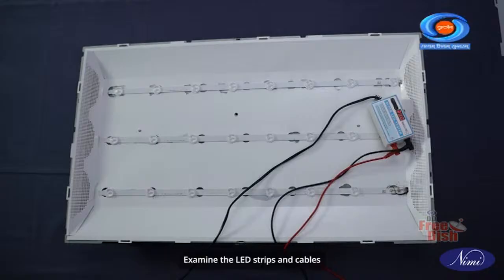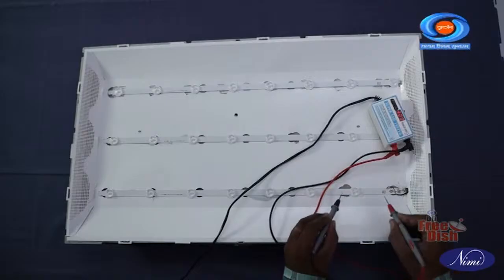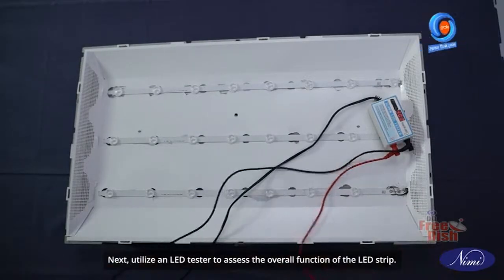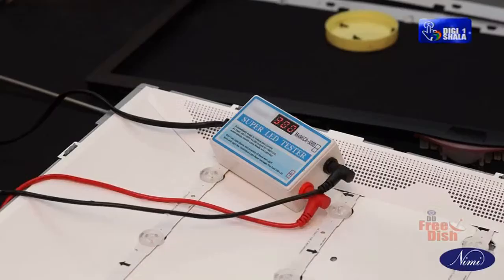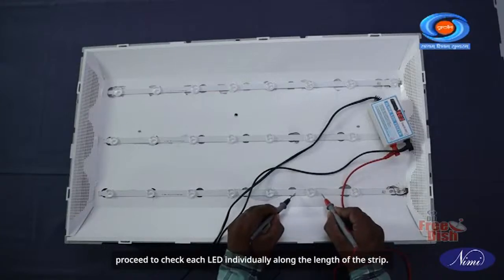Examine the LED strips and cables closely for any signs of damage, wear, or malfunction that may be affecting the TV's performance. Next, utilize an LED tester to assess the overall function of the LED strip. Following the overall function test, proceed to check each LED individually along the length of the strip.